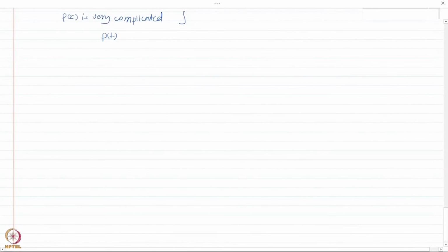Once you understand the Duhamel integral, let us now go into some special cases of non-periodic loading and calculate the response. I would like to start with the step force. A step force is typically defined as a force that you apply suddenly, like a step, and then you maintain it over time. Let us say a load of amplitude p naught is applied suddenly and then maintained over time.